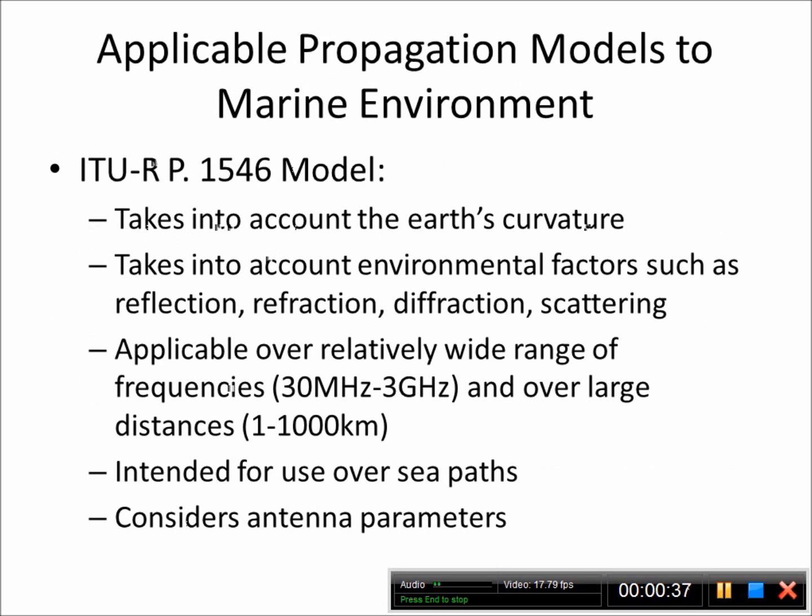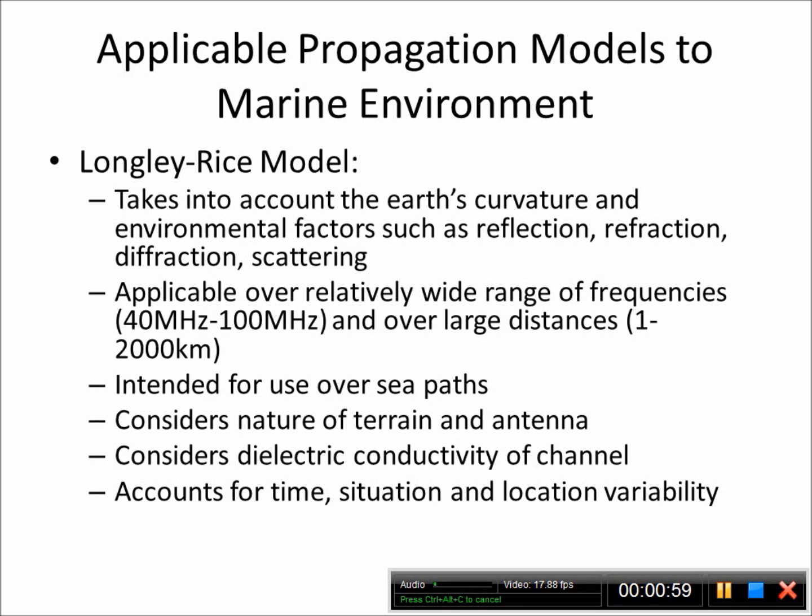Of the models investigated, the most suitable were determined to be the ITU-R and Longley-Rice models. Both are applicable over a large range of frequencies and distances. Both are intended for use over sea paths by considering various environmental factors as well as the Earth's curvature. The ITU-R model also takes into account various antenna parameters, whilst the Longley-Rice model considers both the nature of terrain and antenna, the dielectric conductivity of the channel, as well as time, situation, and location variability.